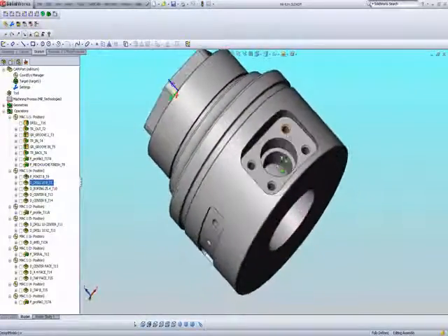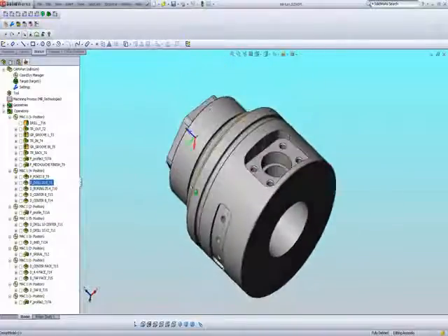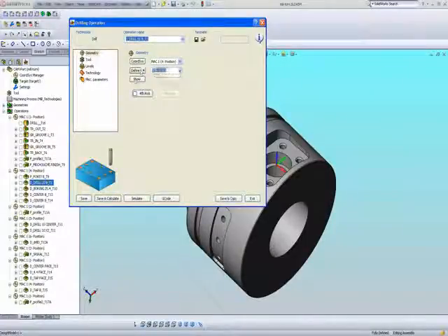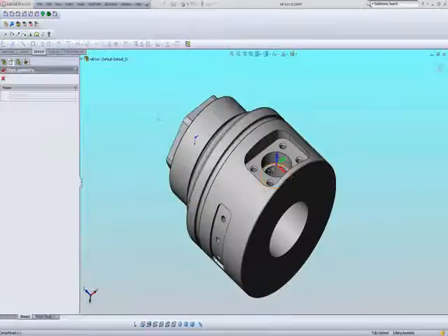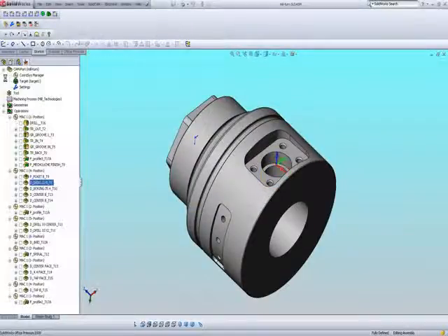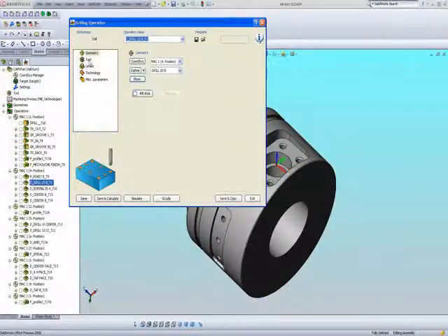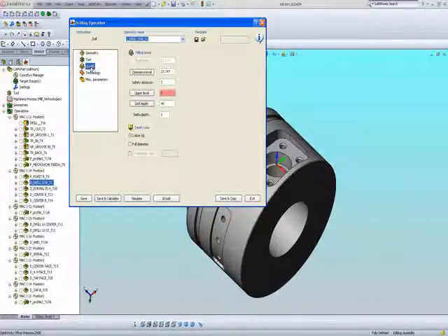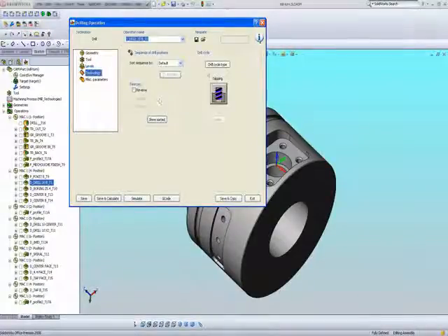Now, continuing in my Mach 1 position 4, I still have to drill out this hole inside over here and these 4 holes over here. So in this particular operation, as seen over here, I've gone through the middle, showing my geometry right in the middle of the part. I've used a simple drill of a 20 millimeter drill. My levels, drill depth, drill cycle type,